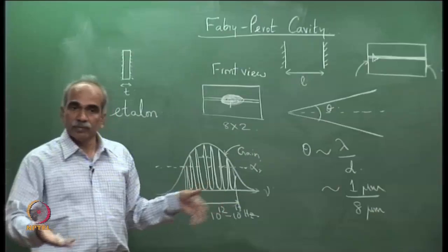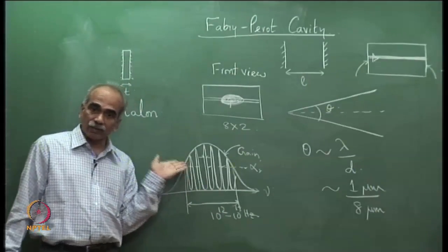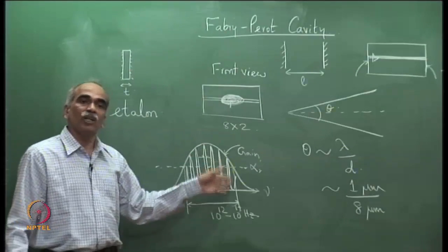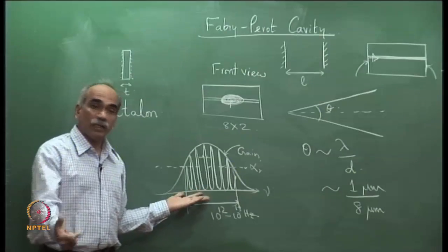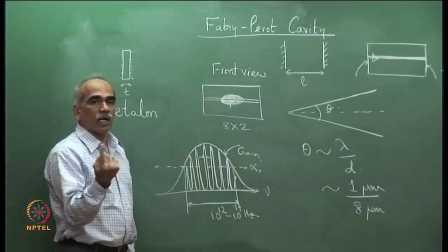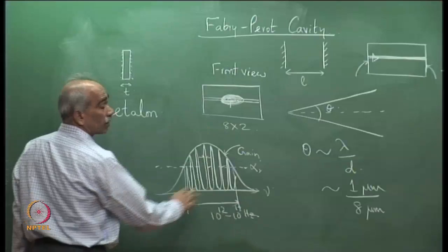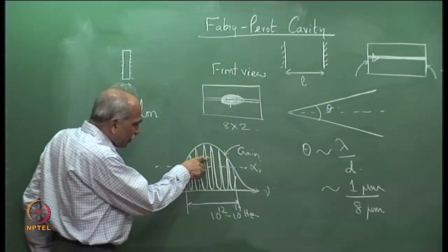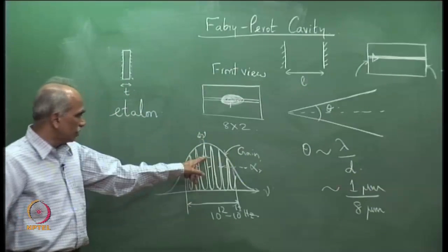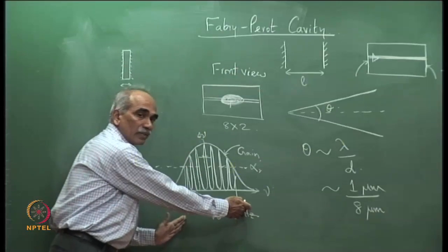In one of the future classes I will demonstrate and show you that these are not just theoretical concepts; you can actually see the multi-longitudinal modes of a Fabry-Perot laser on an optical spectrum analyzer. And when you use a single frequency laser, you will see just one line. The spectrum analyzer is not able to resolve it, it will clearly show you just one line. And the point is, the frequency separation delta nu corresponding to the width of one longitudinal mode is much smaller compared to this.